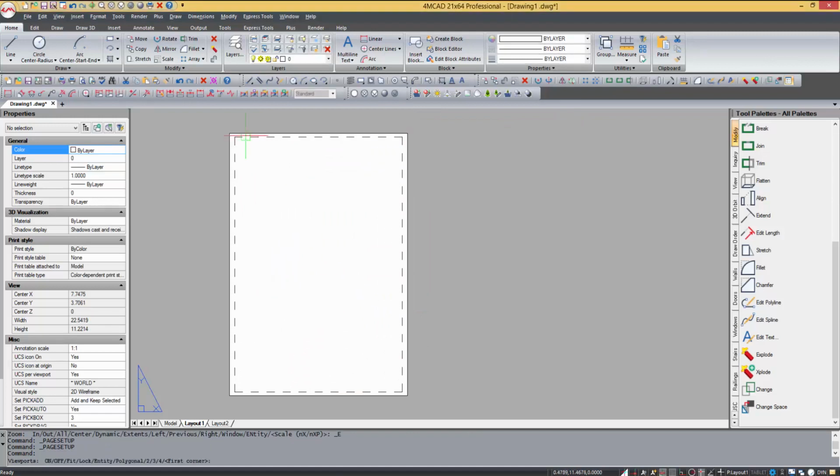Then, typing MV and enter for making a viewport, you should select how many viewports you may need and in what order and orientation. Let's create just 2 viewports. One for the whole window and another for the details of the little flower.